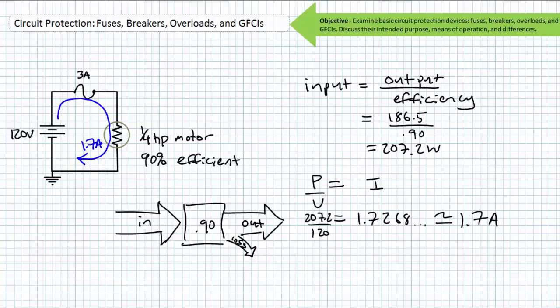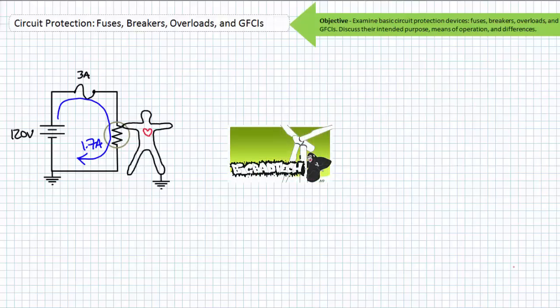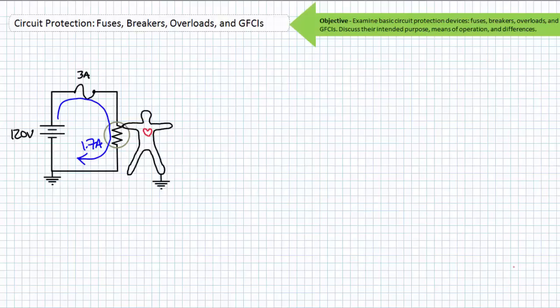That's the point. A large current draw will damage the motor, and replacing a fuse is less expensive than replacing a motor. The fuse only functions when current draw is in excess of 3 amps. Recall from the electrical safety lecture, available at the Big Bad Tech channel, that it does not take a lot of current to kill or injure you if you take that current through especially vulnerable and valuable portions of your anatomy. Let's say your lab partner takes this motor with them into the bathtub. They plug it into an outlet and start taking it apart.